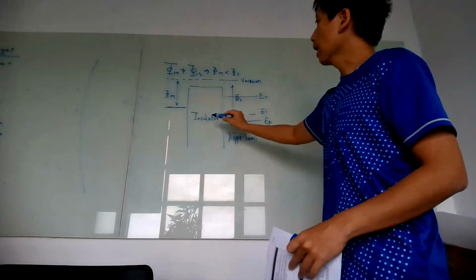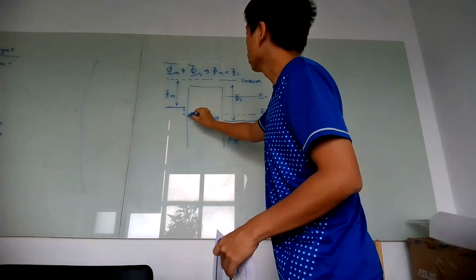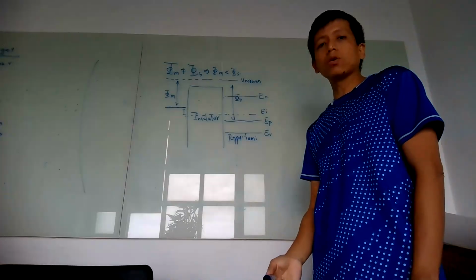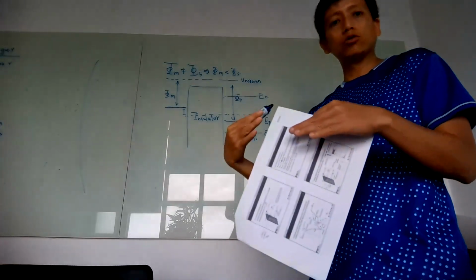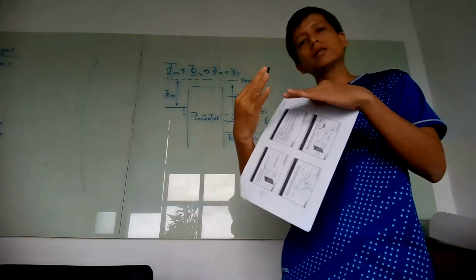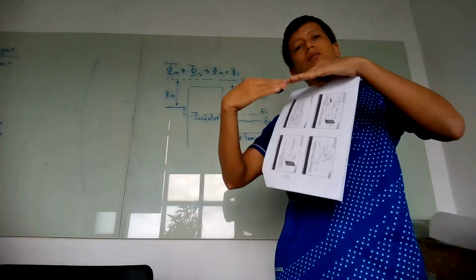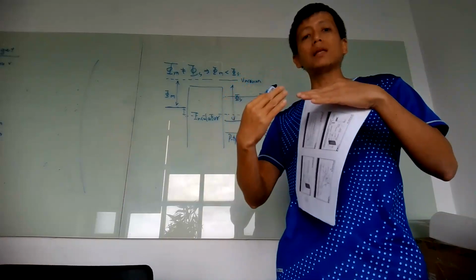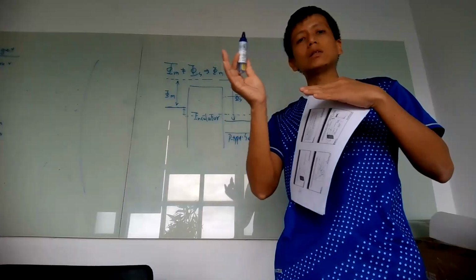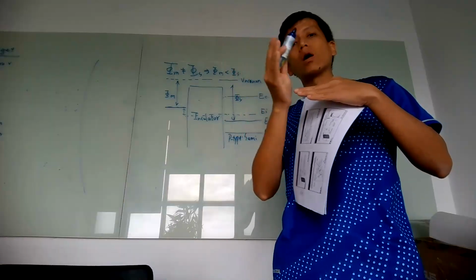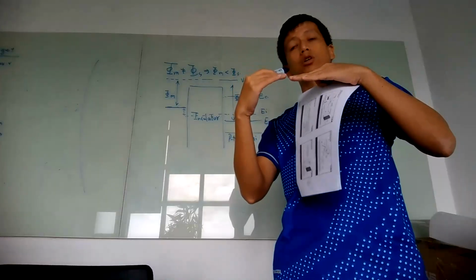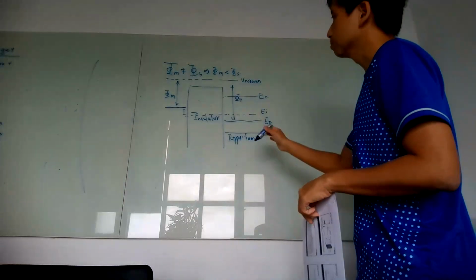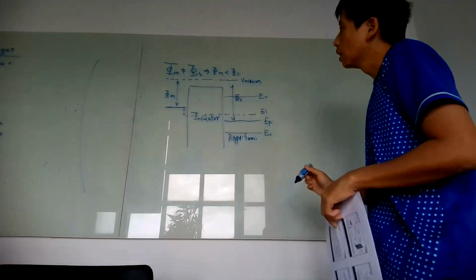For this entire band structure, you can clearly see that the Fermi level doesn't align, and then you get a voltage in between. Okay. And then it is not natural, so we want to align it, just like you get a p-n junction. Once you connect a p-n junction, the Fermi level is not aligned. So what happens in a p-n junction? There will be a built-in potential initially, and you can see free electrons move around. So you align the Fermi level in the p-n junction, and at that time you introduce an internal electric field.